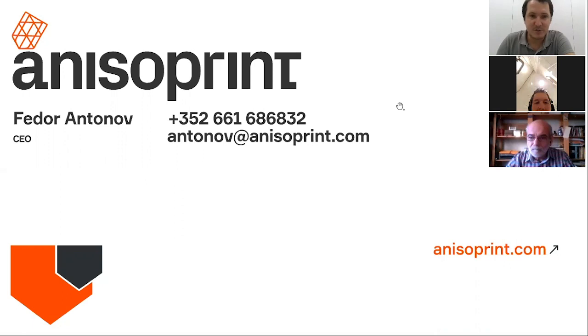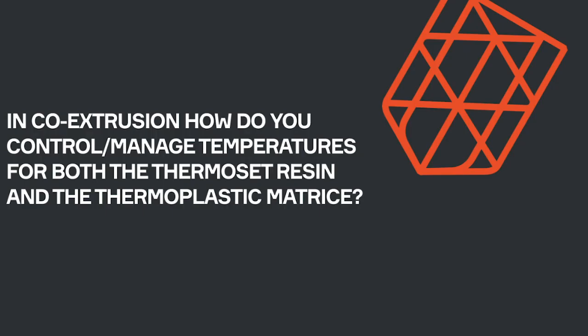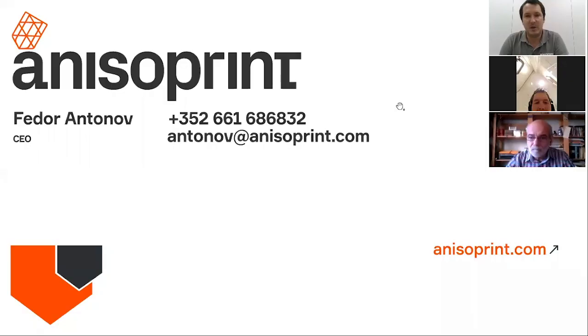Next question comes from Julian. In co-extrusion, how do you control and manage temperatures for both the thermoset resin and the thermoplastic matrix? So both go through the same heat block, and both go through the same nozzle. There is a chamber where the composite fiber mixes together with a molten thermoplastic at a given temperature. So this is the only temperature we control.